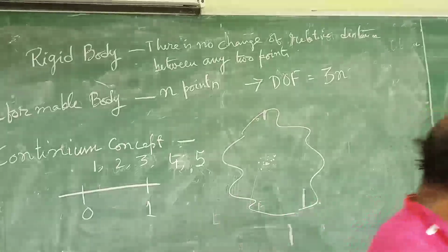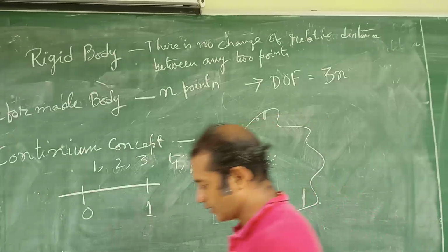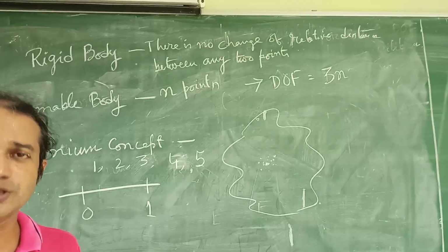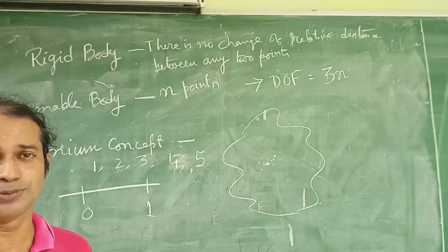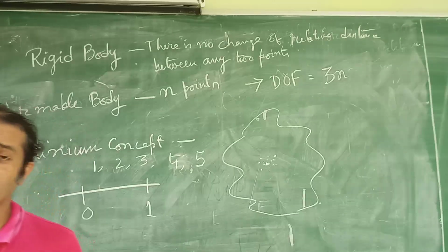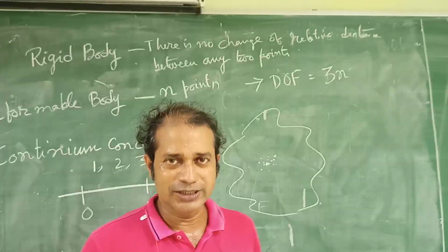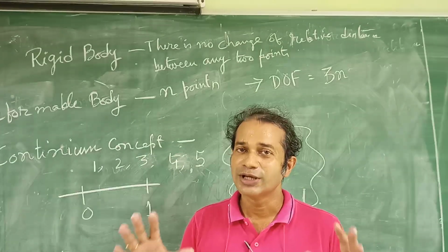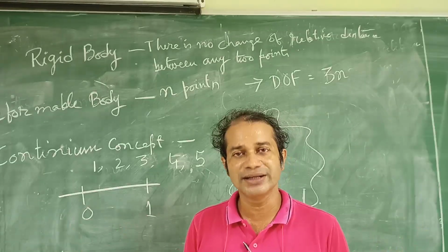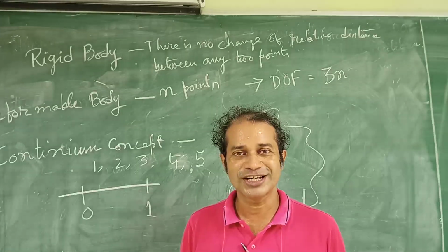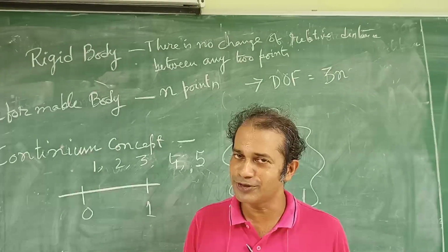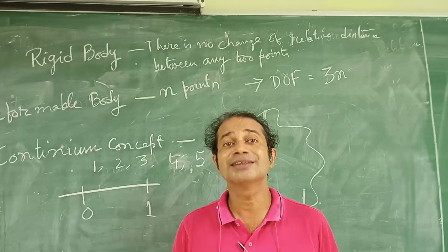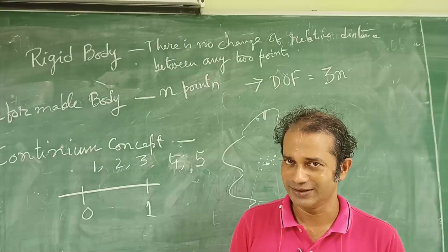Okay, so we will be concluding over here. Out of this lecture, what we take home is that we discussed degrees of freedom. The degrees of freedom is the way the motions are possible. We found that a particular point in 3-dimensional space has 3 degrees of freedom, because the x, y, z are linearly independent. A straight line in 3D has 5 degrees of freedom. We calculated it geometrically and demonstrated it in physical motion as well.